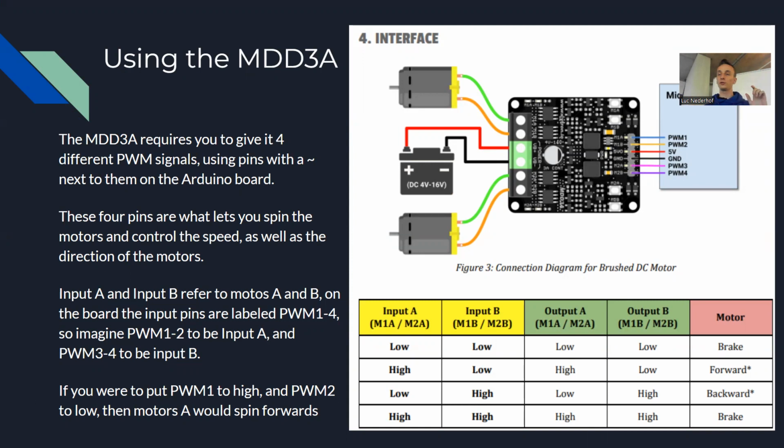What you want, if you are trying to move, is to have it going one direction and not the other. So setting one of those PWM signals to high and setting the other one to low will allow it to spin in a certain direction. And whichever way you do that depends whether you go forwards or backwards. So if you alternate these, you've got movement going.